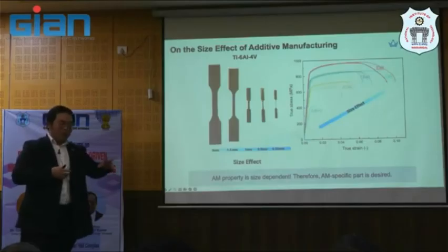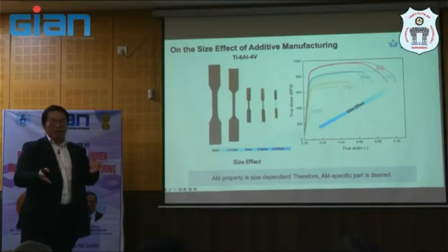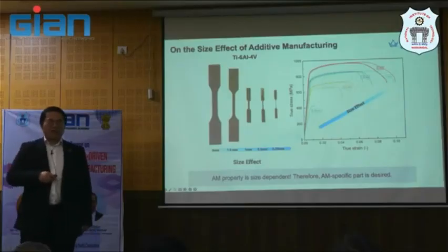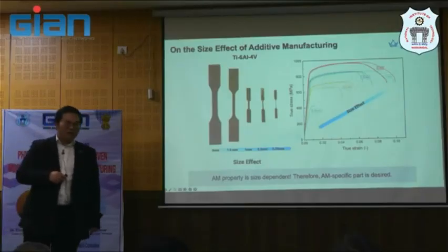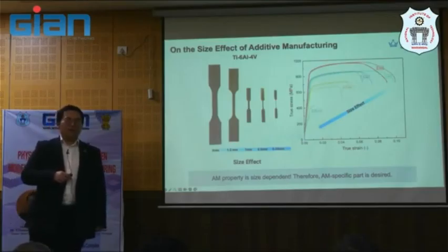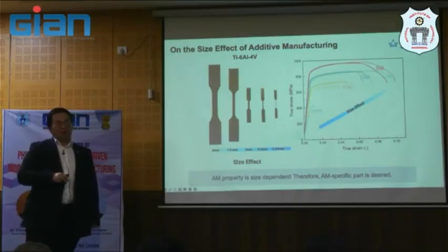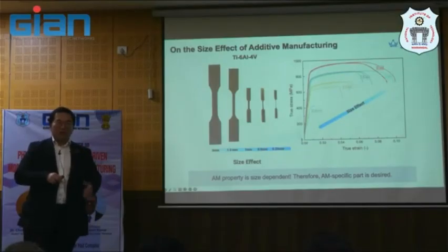But they do both as-fabricated and as-heat-treated. That paper is probably in Acta Biomaterialia, or Materials and Design, something like that. Back in 2014, 15 as well, so 10 years ago. I think, off the top of my head, probably a little bit, not a lot. But again, that is based on Ti-6Al-4V. It's not nickel-based superalloy. If you want, you can design for nickel-based superalloy.